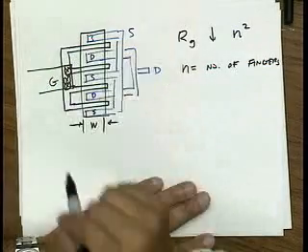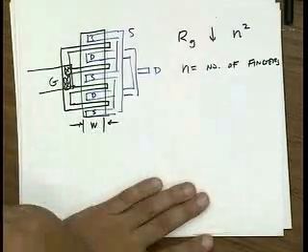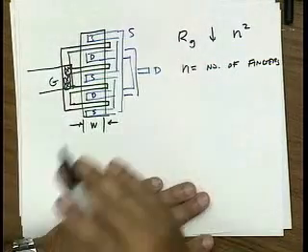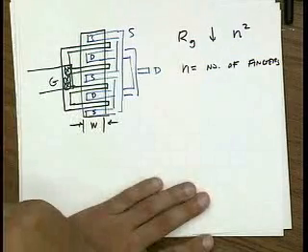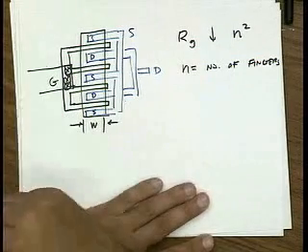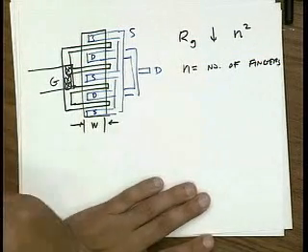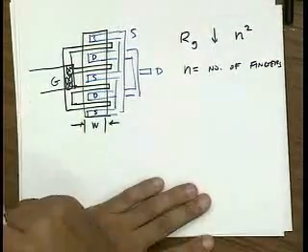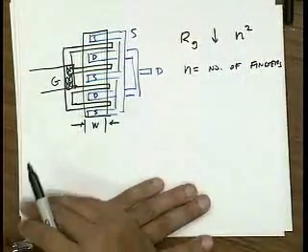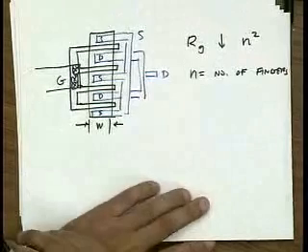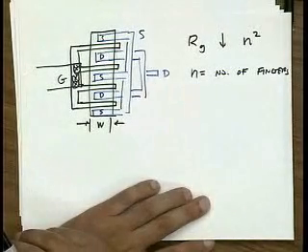So if I need to go from top metal, let's say metal 6, all the way down to poly, I'm going to have 6 series connections of vias, each on the order of 5 ohms, right? So we're talking 30 ohms per via. I better put a lot of them in parallel to bring that down to a few tenths of an ohm if I don't want it to hurt my noise figure. Okay.